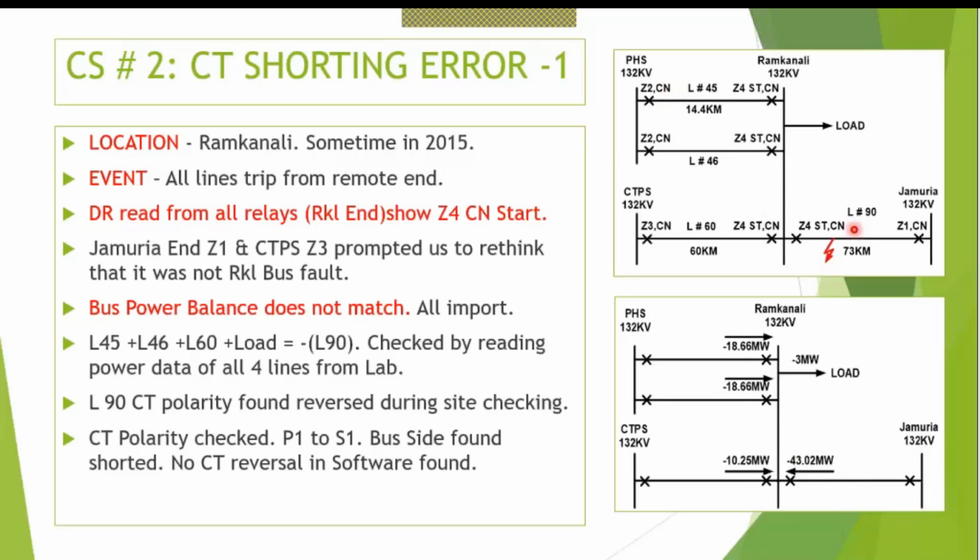These lines tripped okay, this line tripped okay, because this line did not trip, that means the other end has to clear the fault. See how this zone 1 did not clear, and the backup I was talking about, zone 2, is clearing the fault. This one is a longer line, the infeed from this line is more. So see, this fault is occurring in zone 3, not in zone 2. Although, as far as I remember, the zone 2 should cover this fault.